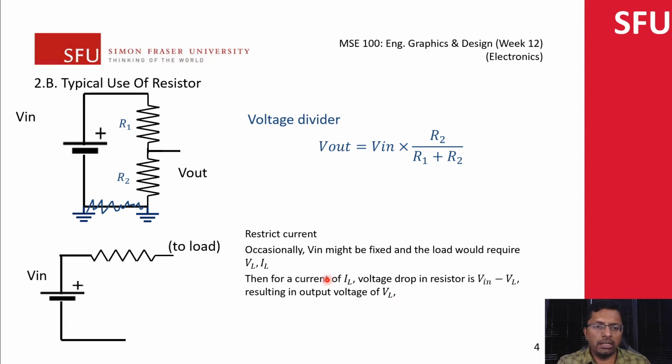So this is maybe not a resistance but a more complicated circuit, maybe your cell phone, which, for instance, with a USB needs 5 volts going into it, and you've done the calculation and you know exactly the current that's needed. In that case, you can still drive the load using a higher voltage, as long as you add a resistance in series.